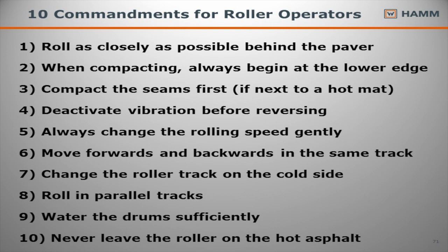Never leave the roller on the hot mat, but 99% of the time, every time I go on a project, when the paver stops, where's the breakdown roller? Right behind the paver. If you're going to stop behind the paver, hopefully you can get off and get onto a cold mat or a shoulder somewhere. But don't sit on the hot mat.